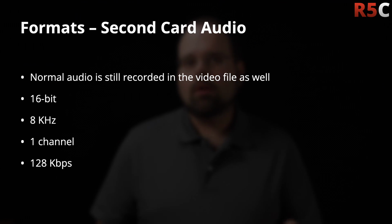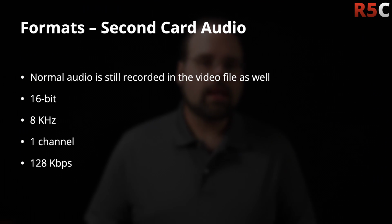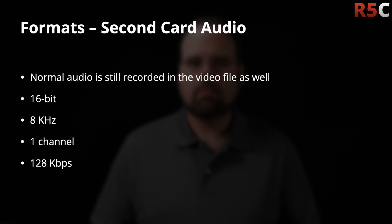It, however, is only 16-bit. Its sample rate is only 8 kilohertz, which completely decimates, for lack of a better word, the audio quality. It's really only going to be good for voice, and not in a really high fidelity context. It's one channel only, so it takes all of the audio tracks that the camera is recording and downmixes that into a single channel. Now, this file is relatively small. It's only 128 kilobits per second worth of data, and it is separate from the regular audio that you are recording.